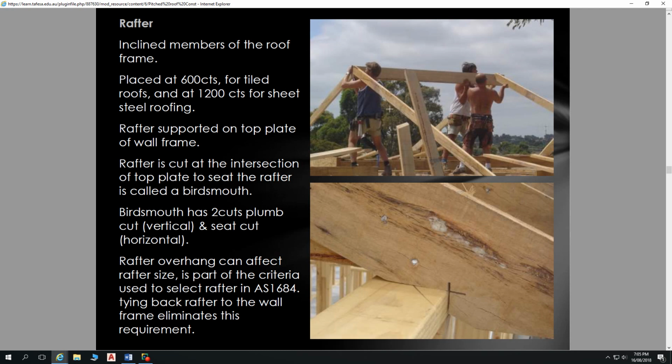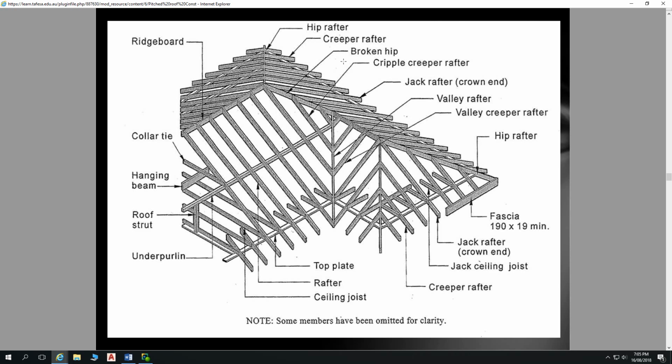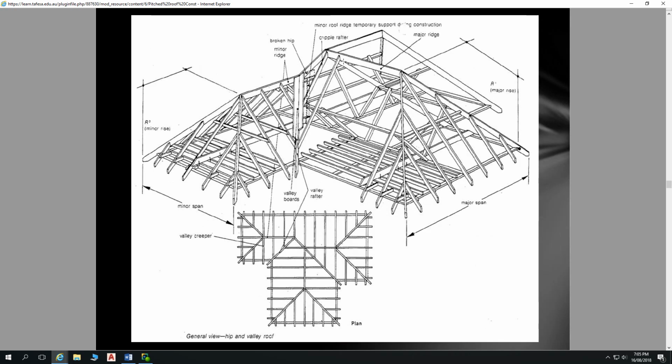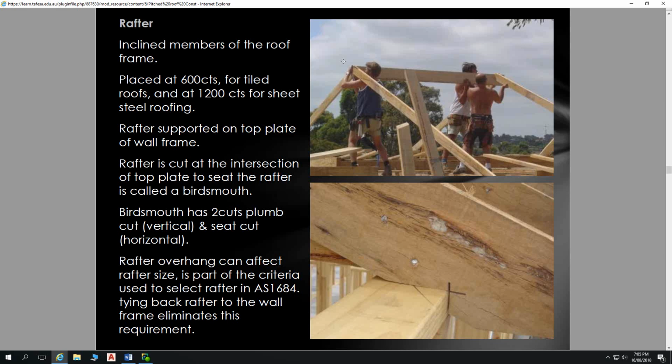But when we have tie downs, we have to carry those tie downs, or the tying capacity, all the way through our frame. So first of all, on our frame, there's a good picture to show this. I'll go back to where we were. So typically on our frame, we're going to have some battens across here.